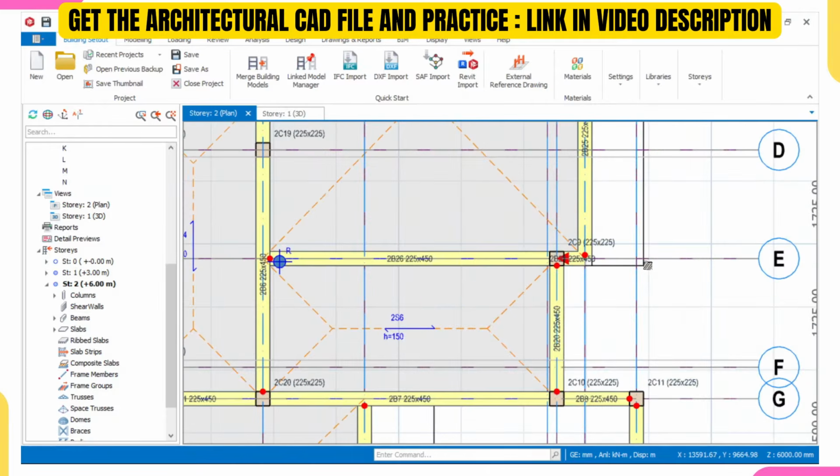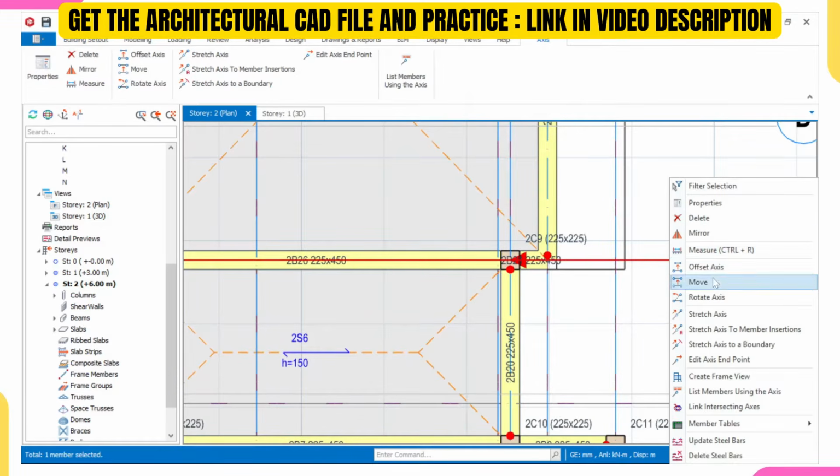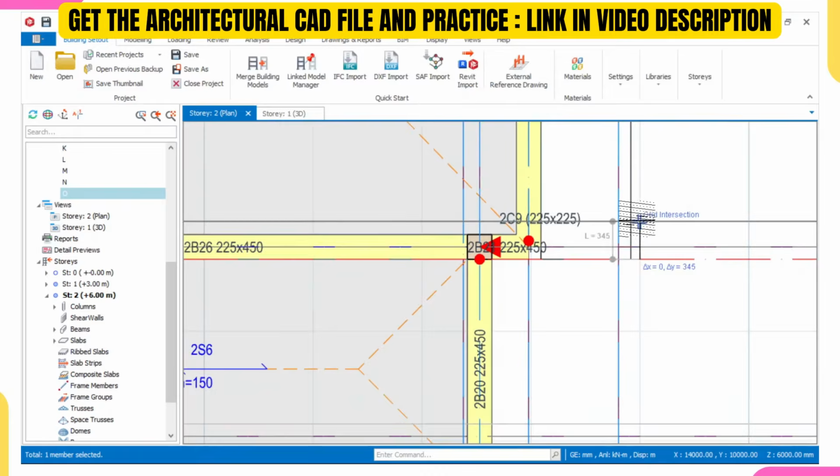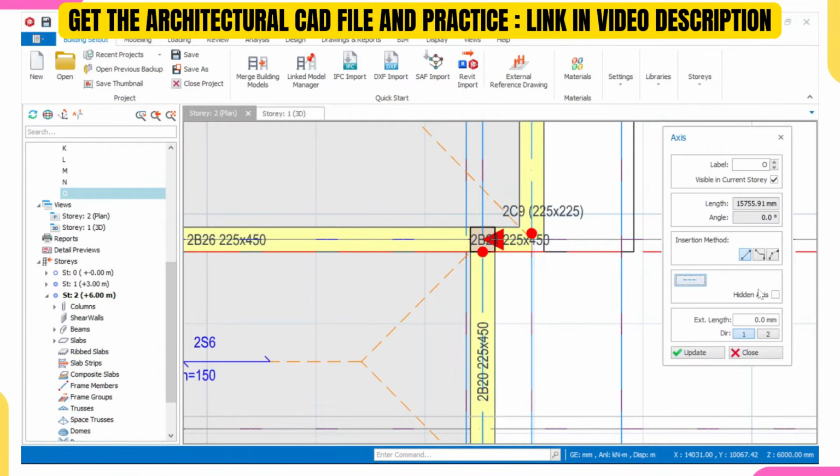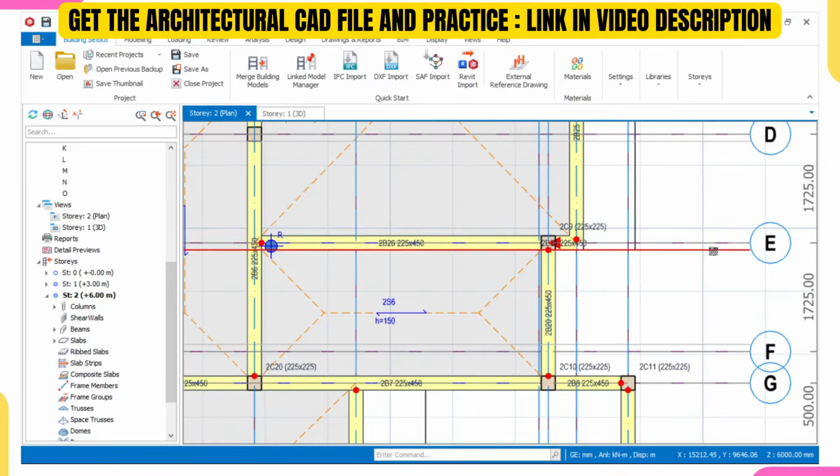Okay, I want to do this for this one. So I'll click on this, right click on it, click on offset axis. Then I'll place a grid line at this point. I'll escape, right click on Property. Then I'll turn off this, then click on hidden axis. I'll then click on Update. So look at it, it's now a hidden axis.